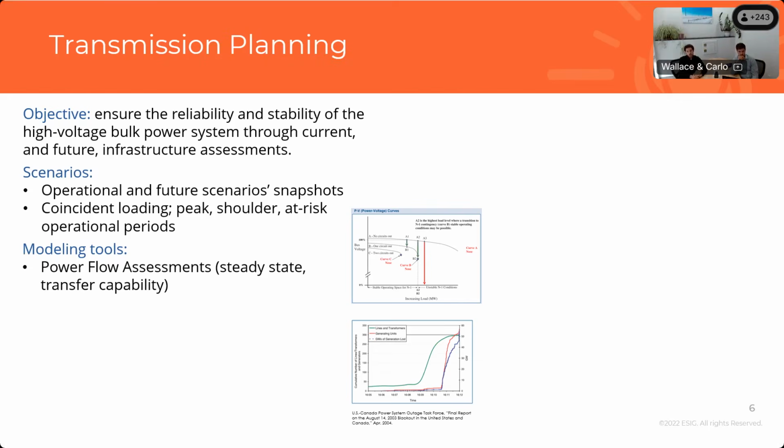The other type is transfer capability. Now, this is where we'll be looking at the voltage stability aspects from a loadability perspective. And that's understanding how close to an instability point, which Sam talked about at length yesterday, you might arrive at based on the loading of your system.